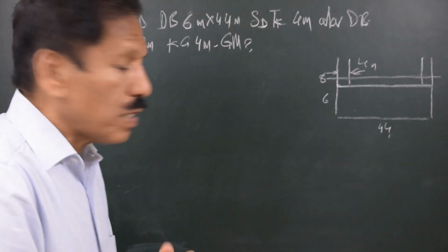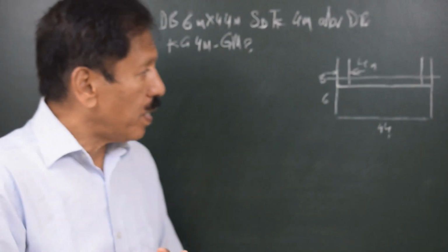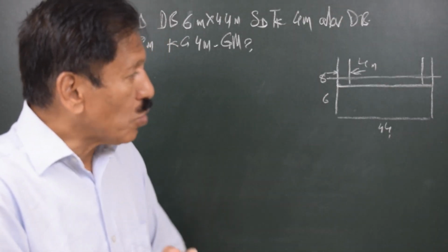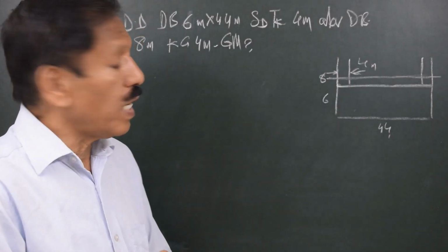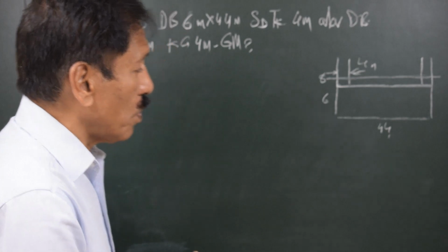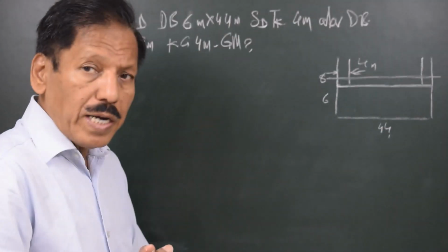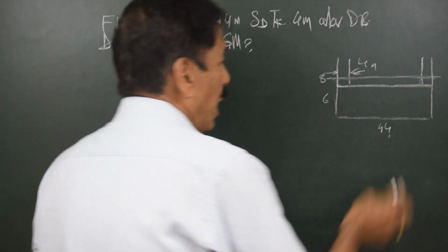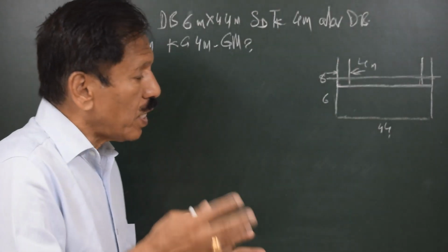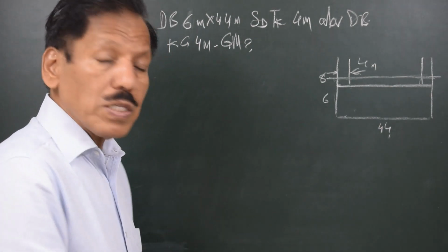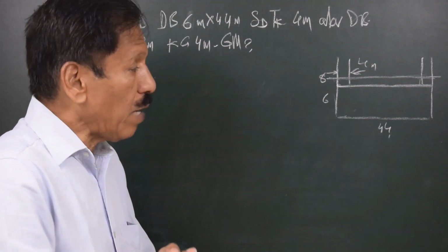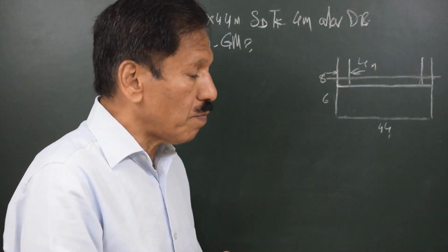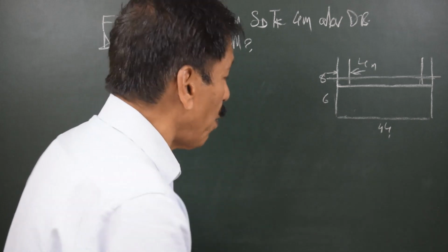Now the first thing we should do in such a calculation is look at the transverse profile of the craft. It looks like the transverse area is the same all over the length. That means if we take any transverse section anywhere along the ship's length, we see the same transverse profile. If we find the centroid of this area with respect to the keel, that distance will also be the KB of the craft. So instead of involving the full length of the vessel, let us find the centroid of this transverse area by taking the moment about the keel.